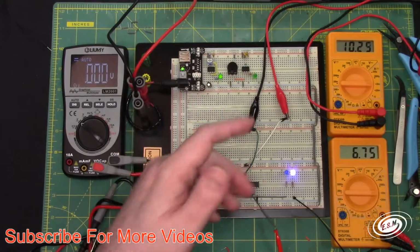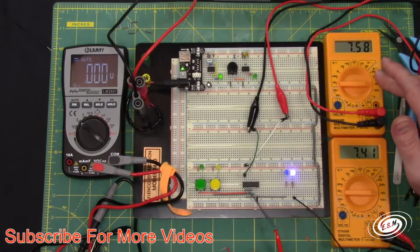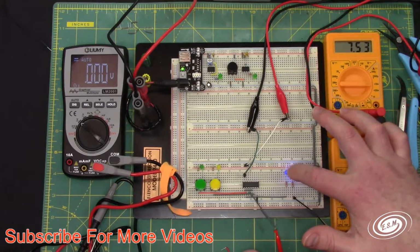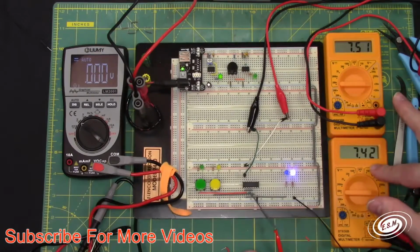So I'm going to turn on the circuit. It's going to start in the reset position, and as you can see, the chip itself is drawing 7.5 milliamps, lighting this LED, and the LED is drawing 7.42.